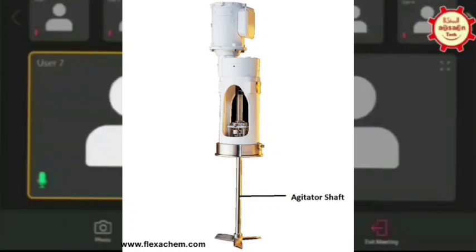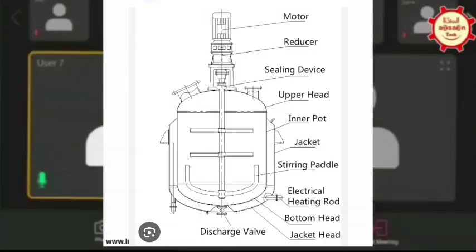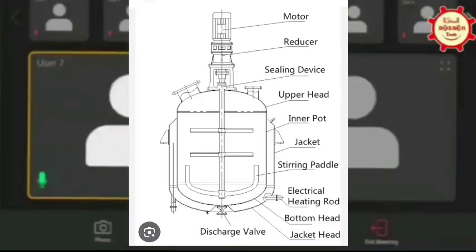What is your issue? Okay, I will explain what the case is. First, there is an agitated reactor, and there is a gap provided between the bottom impeller, which is an anchor, and the bottom dish, of 11 mm. I want to check that, due to thermal expansion, the shaft is going to expand linearly. So is the 11 mm gap sufficient, so that during operation the bottom impeller will not touch the bottom dish?